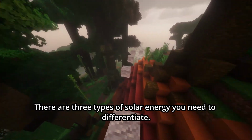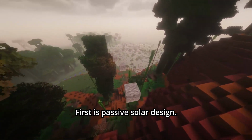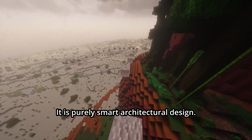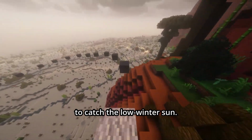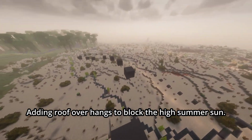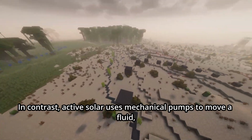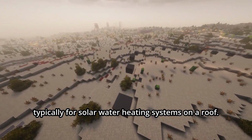There are 3 types of solar energy you need to differentiate. First is passive solar design. This doesn't use any mechanical devices, pumps, or technology. It is purely smart architectural design. Think of building a house with large south-facing windows to catch the low winter sun, adding roof overhangs to block the high summer sun, and using dark building materials to naturally absorb and hold heat. In contrast, active solar uses mechanical pumps to move a fluid, typically for solar water heating systems on a roof.